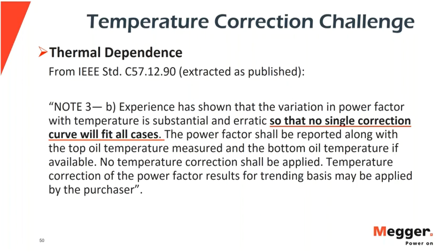Megger, like it was described during this webinar, has developed the individual temperature correction based on fundamental principles, based on the Arrhenius equation, correlating the temperature change and its effect depending on the condition of the insulation system itself, based on the dielectric response that you get. So now that we have a unique dielectric response obtained from one specific transformer, we can estimate the thermal response of that specific transformer.